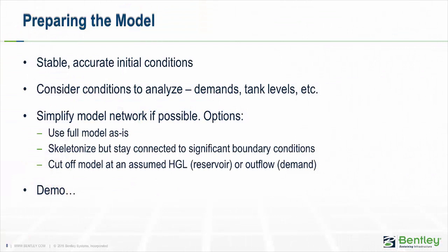Okay, so what do you need to do to prepare the model? So if you have a WaterCAD or a WaterGEMS model, first thing is you want to make sure that it's in really good, stable conditions. So, make sure it's calibrated. You don't have any issues with the model being unbalanced, or any issues like that. Hammer is a little more sensitive to those kind of things than you can sometimes get away with in a WaterGEMS model. So you want to make sure that your initial conditions are nice and accurate.